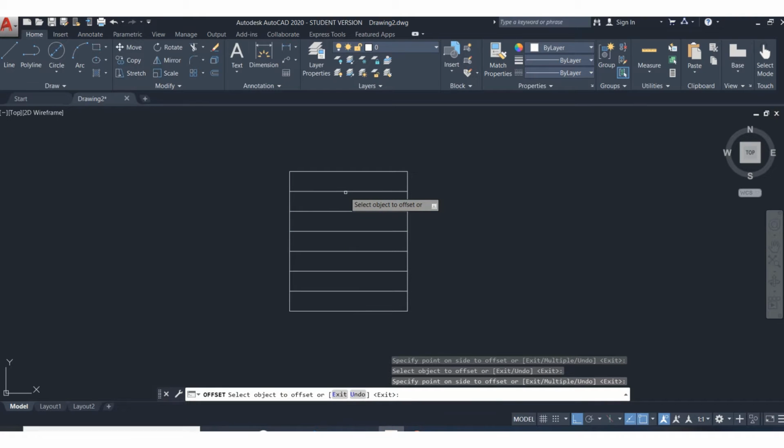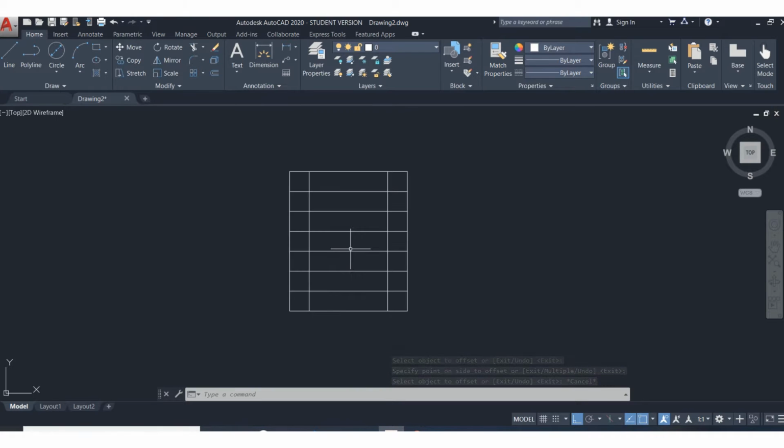And now this is unusual in this drawing, that everything is 1 inch, but I can also do the same on the sides. Take that line, offset it to the right, that line, offset it to the left. I'm going to hit escape to finish that command. Now again, that's pretty unusual that everything is 1 inch, but it's a good demonstration of the power of that offset tool. So now what I want to do is eliminate the stuff that I don't want here.